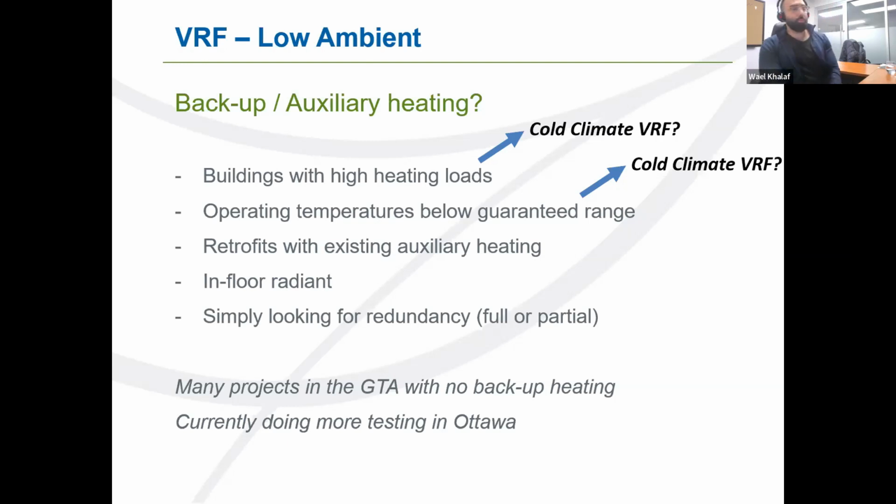So what we've done in Ottawa is we've bought one of our low ambient, low climate heat pumps, and we installed it on the roof of our building, and we installed a fan coil inside our warehouse. We're doing testing right now to see what temperature in Ottawa we're going to measure in the winter, how much capacity the unit will provide down to -22 or below, and at what temperature the actual unit will trip. This is testing we're going through this winter. So we'll have some good data, some interesting information to share with whoever is interested about how this air source heat pump will behave in a very cold environment for heating.